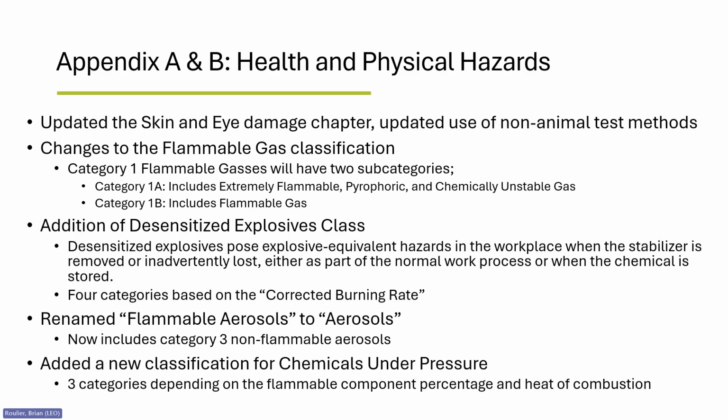Desensitized explosives are solid or liquid explosive chemicals to which a stabilizer or desensitizer has been added. These chemicals pose explosive equivalent hazards in the workplace when the stabilizer is removed or inadvertently lost, either as part of the normal work process or when the chemical is stored. Another hazard classification change in this section relates to renaming the flammable aerosols classification to just aerosols and including a third hazard category for non-flammable aerosols. A new hazard classification, chemicals under pressure, has been added with three categories depending on the flammable component percentage and heat of combustion.